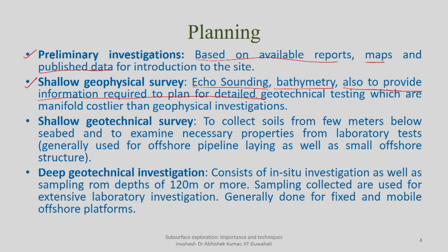So, preliminary investigation gives you an idea of which method of geophysical investigation to use, or whether it is required at all, and collectively, based on your preliminary investigation and the findings from the geophysical survey, you can plan for detailed geotechnical investigation. Remember, in comparison to geophysical investigation, geotechnical investigations are manifold costlier.